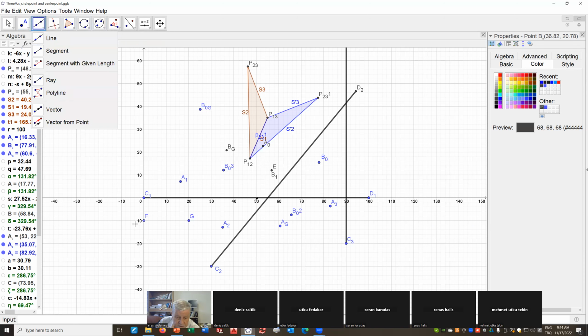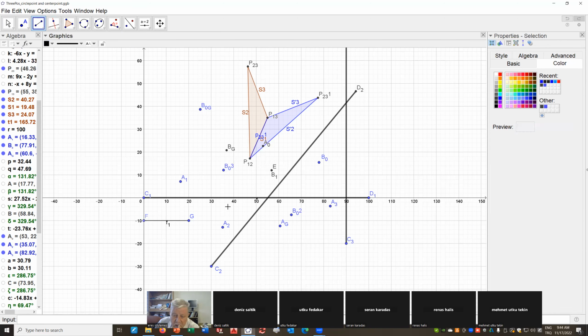Let us say this is our fixed frame. When moved from C1, D1 to C2, D2, the inverse motion will be, I will move C2, D2 back to C1, D1. In order to do that, I will be rotating C2, D2 about P12 by an angle minus phi12, correct?